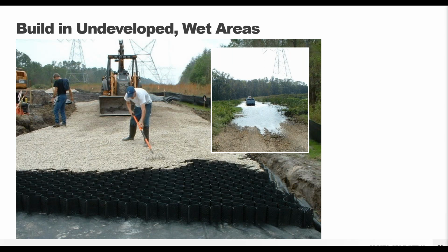So with GeoWeb panels, you can create what is essentially a bridge over that soft, wet ground. So it's where you're going to cover that wetlands area and create that mattress effect so that you don't have that punching into your wetlands area. Those saturated soils typically can't support any type of vehicle load. So with the GeoWeb system, you can bring in that AASHTO H20 loading, your full emergency vehicle loads, highway rated loads, and that can be a great way to get that in there. And like I said, those clear stones, the washed minimal fines content, is what really is going to allow you to have that water flow.